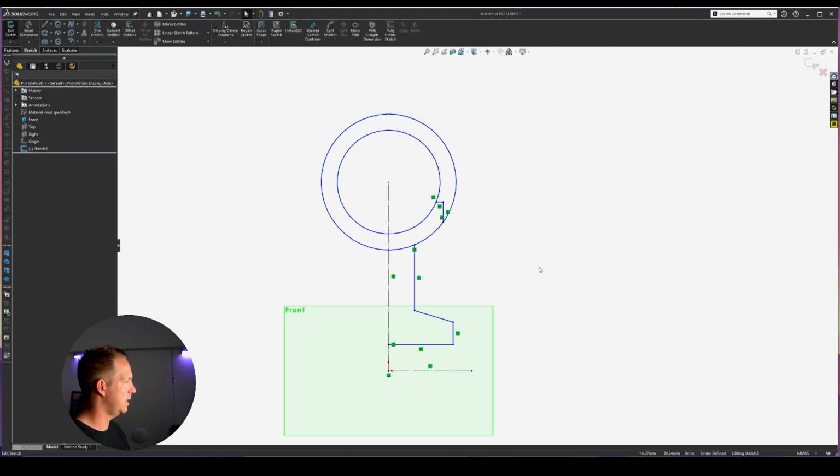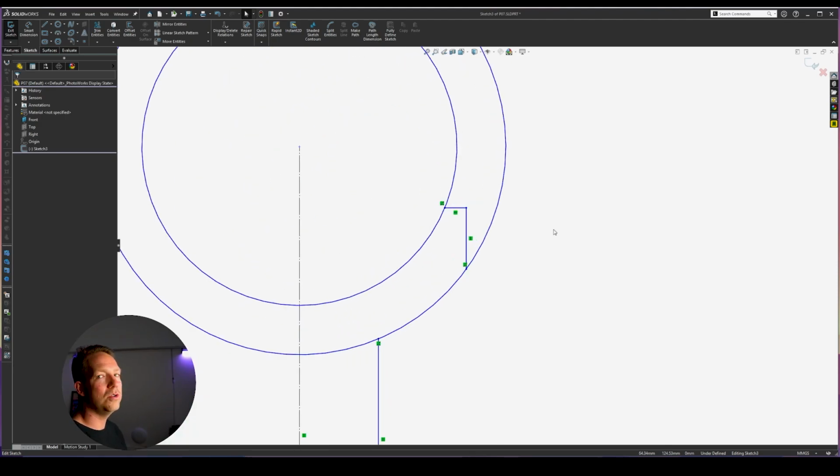Now, when editing the sketch, or in an assembly, you can see the note fully defined. You will also see underdefined and overdefined. What that refers to is what kind of control you have on your geometry. So the example here is that every blue line you see is underdefined. What that means is there's no dimension or relation added to it that controls its position in space.